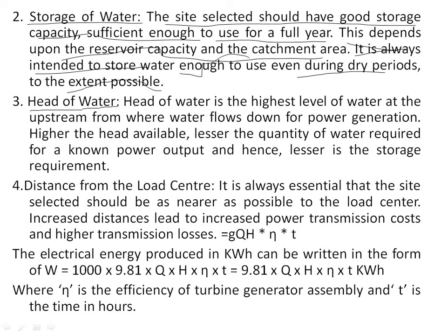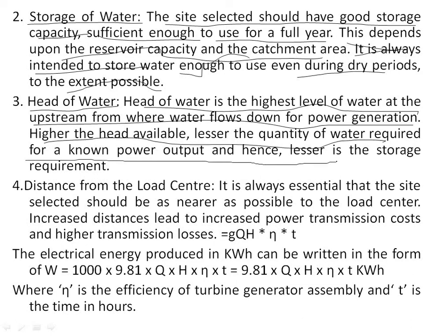Third one, that is head of water. Head of water is the highest level of the water at the upstream from where water flows down for the power generation. Higher the head available, lesser the quantity of water required for a known power output, and hence lesser is the storage requirement. You all got this point.